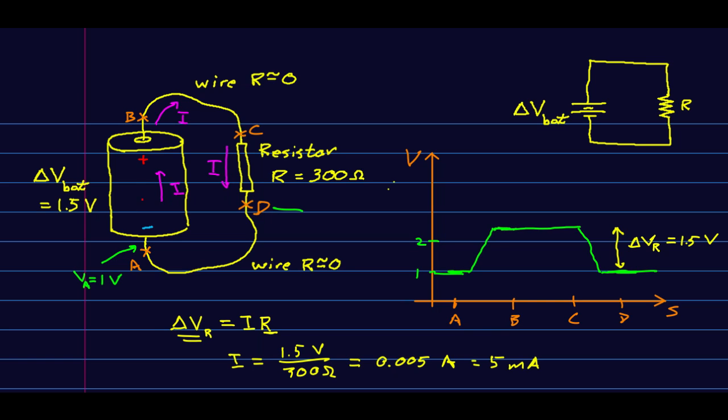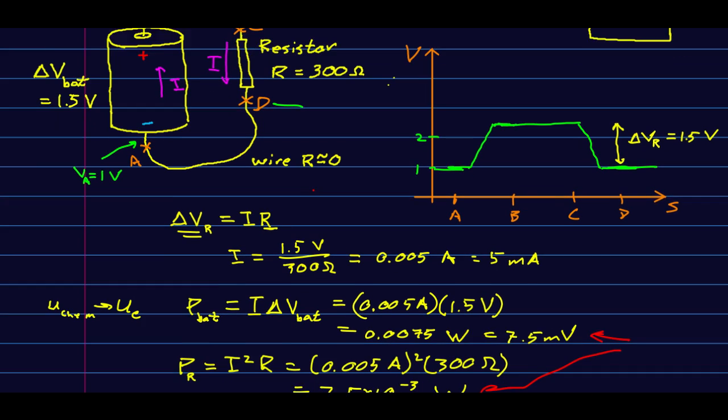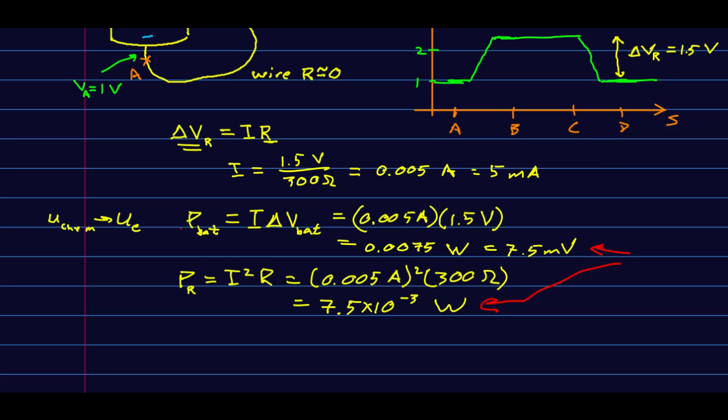No, all of the energy you put in with the battery is dissipated. It leaves the circuit by being turned into thermal energy in the resistor. And so you always find in resistor circuits that the power in, which is generally at the batteries, always equals the power out, or the power losses, which are usually in your resistors.